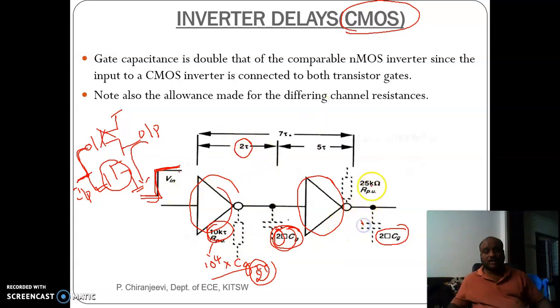Similarly, on the other end, in the CMOS based circuit, pull up with the PMOS and pull down with NMOS, this is the input and this is the output, supply and the ground. As this inverter is giving an output of low from high to low, a low input is applied here, so we make the pull down transistor off and the pull up transistor on.